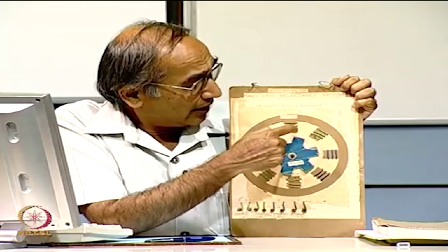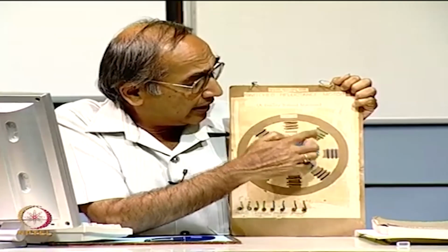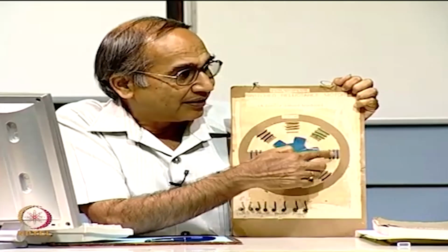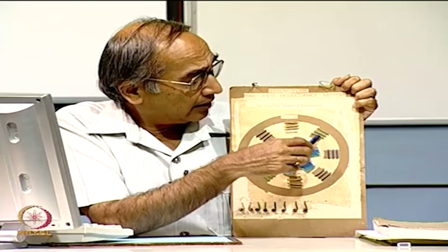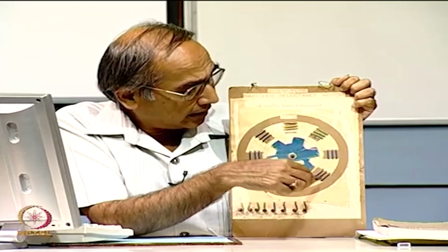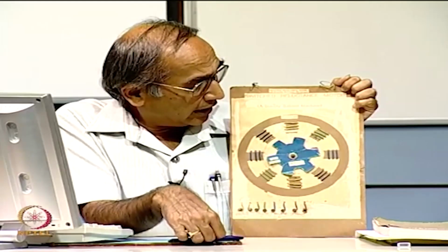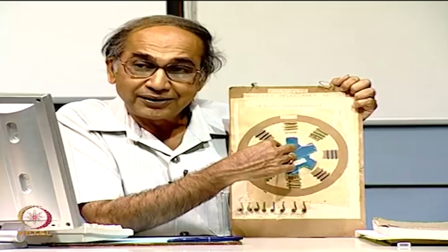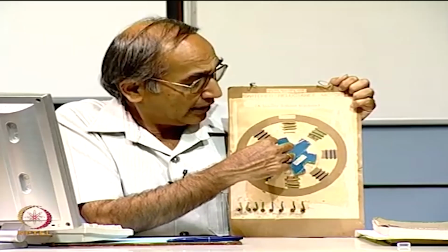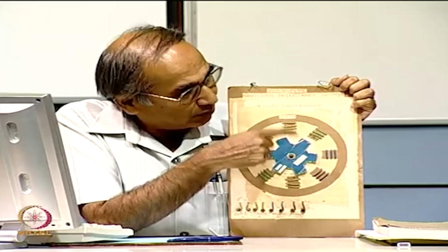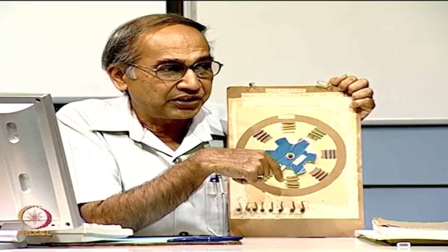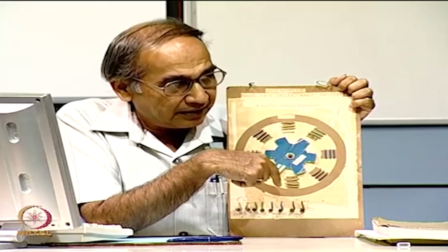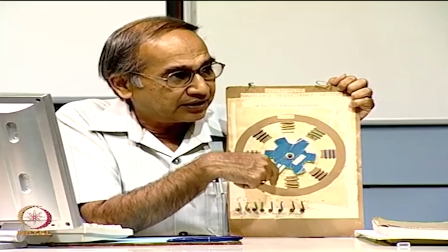So, you will notice that while you are switching in this sequence, from yellow coil, green coil, blue coil and black coil, actually it is moving in the other direction. So, if you go the other way around, it will move in the opposite direction. So, you can change the direction by the appropriate switching, and you can change the speed by changing the switching speed.